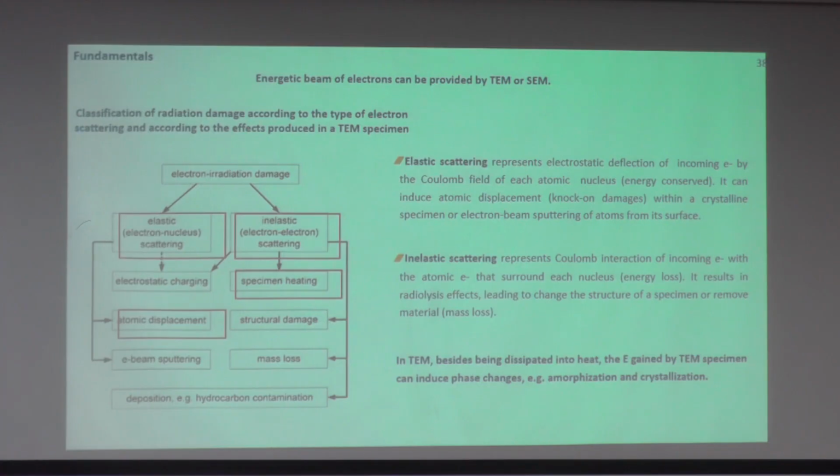The elastic electron scattering can lead to electrostatic charging, also to atomic displacement and ion beam sputtering. The inelastic scattering can lead to specimen heating, also to structural damage, mass loss and deposition.